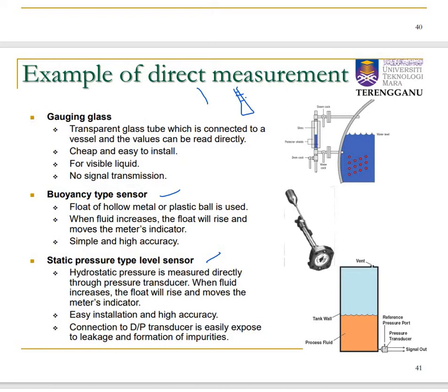So basically that sensor is floating. For example, like this, we have a liquid here. The sensor is floating at the top of the water level. So it will increase until a certain limit, until the maximum limit, and then if the water already achieves the maximum limit, it will cut the water that feeds into the system.